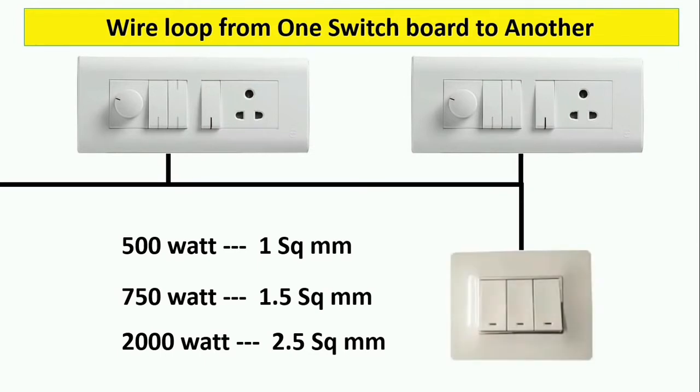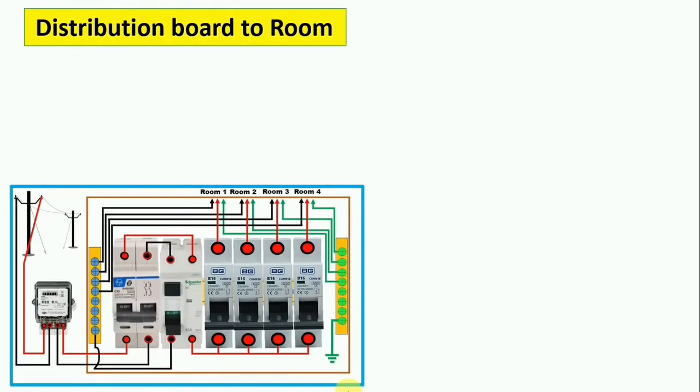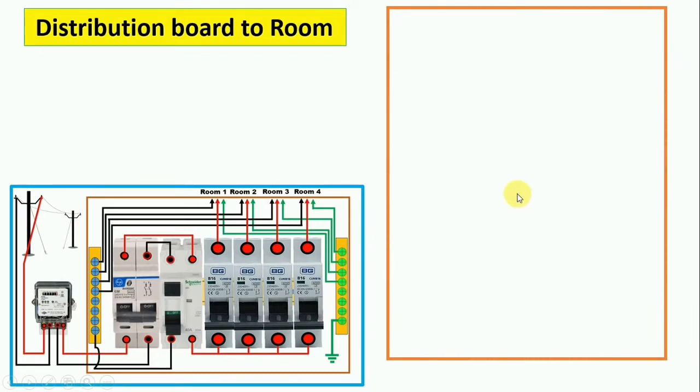Now 2.5 is usually for our heaters. Our socket outlets mostly use 2.5, because it's expected that you might want to connect a heater, a kettle, an iron or a freezer. That's why most of our sockets are basically 2.5 mm.